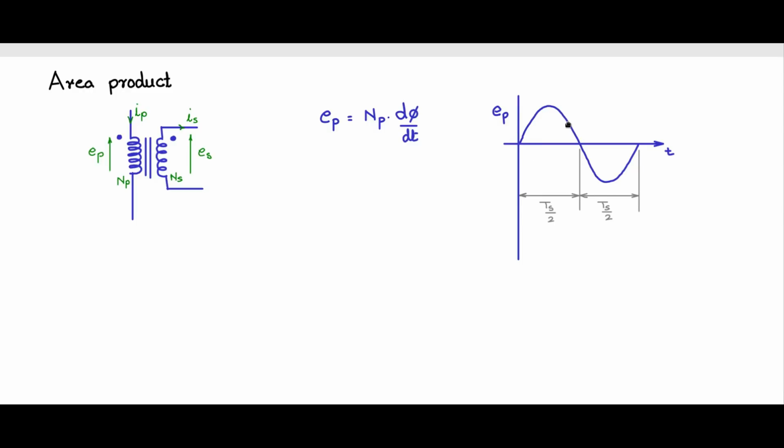Now we are not that much interested in the wave shape as we are interested in the area under the curve, especially for design of the transformers. We are bothered about the volt second, or the area under the voltage profile, this one. So this volt second we need to be worried about. Now this volt second and the equivalent square wave volt second here, let us say we have an equivalent square wave, flat top. Both these will have the same volt seconds.